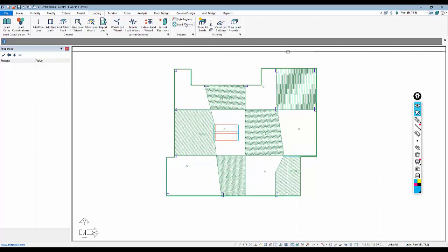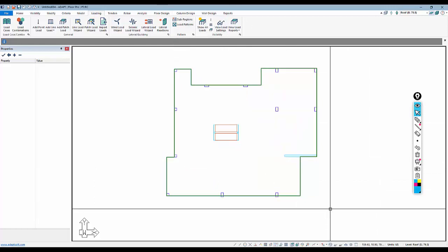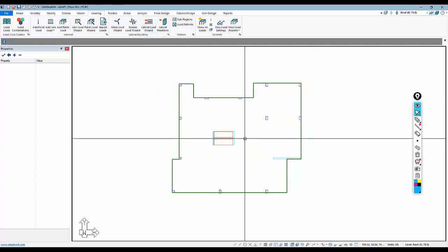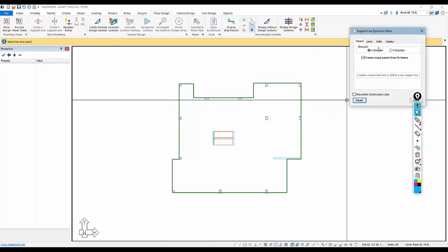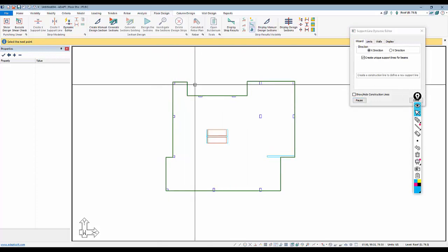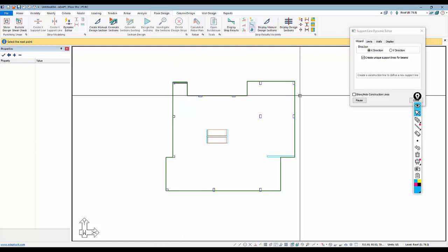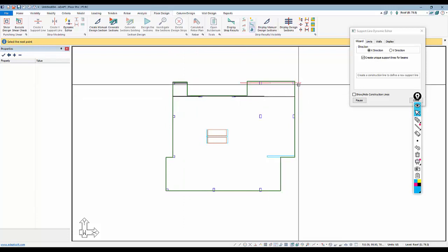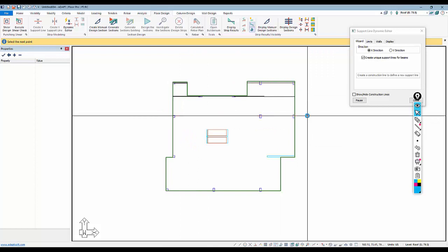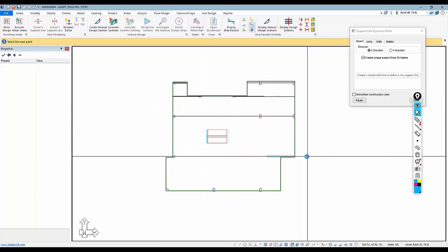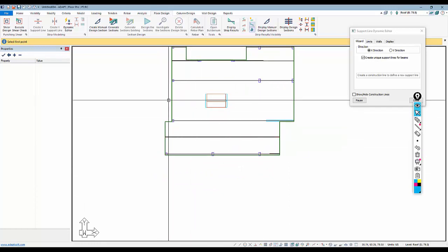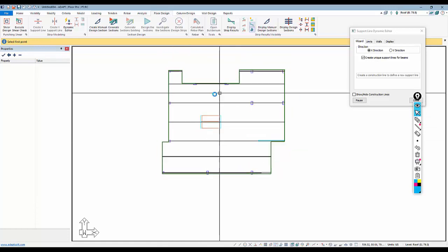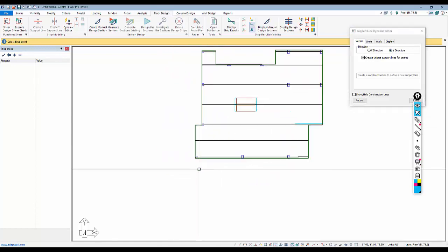I'm going to go ahead and go back to my default display. I'm going to set up some design strips here so we can look at that process for evaluating the patterned combinations. I'll use the dynamic editor, and we're going to use the X direction first. So we're going to assume this is just an RC slab. We'll just add some strips here. We might want to add a few middle strips, so we'll add a strip right through here. Okay, and then I'll switch this over to the Y direction.